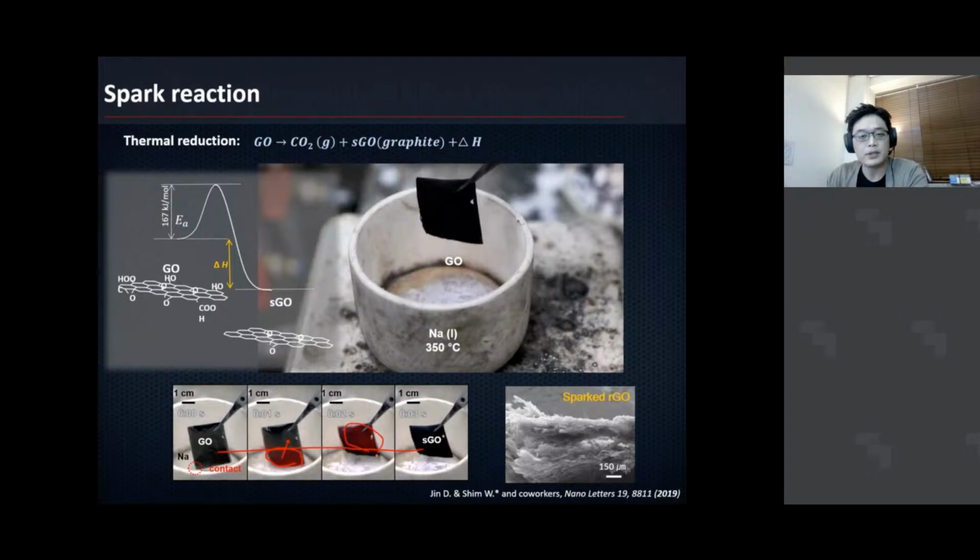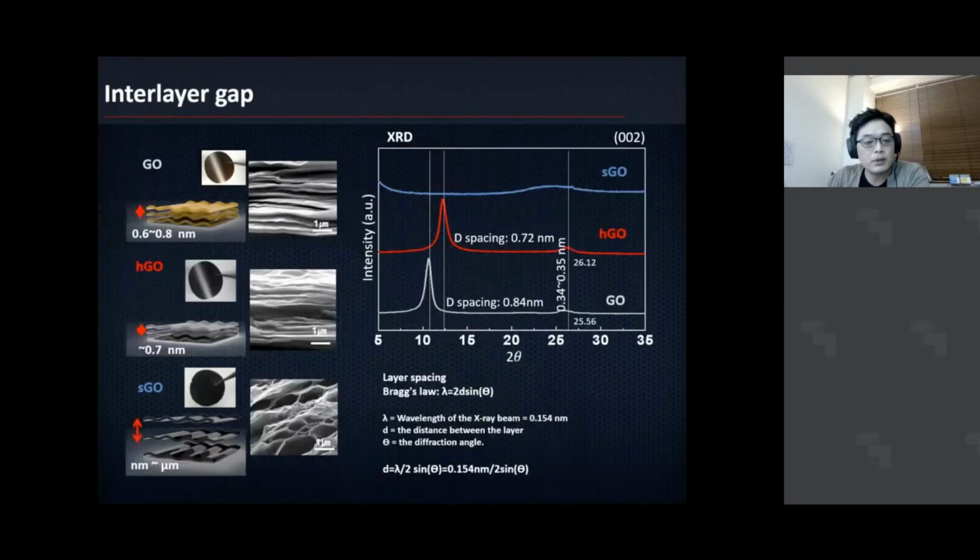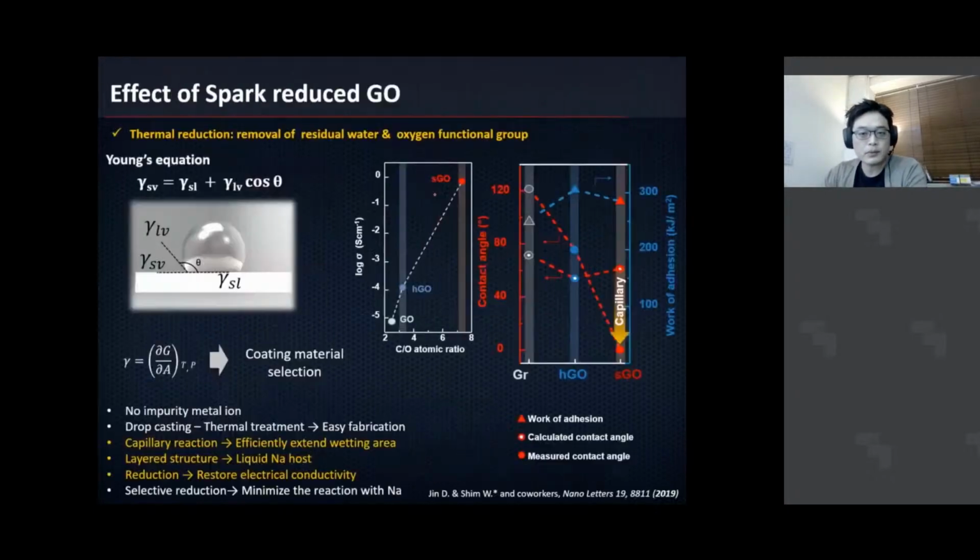That's the fires on it. Okay. So after that, if you look at the microstructure, the morphology of that microstructure, that's the typical graphene oxide. There are many gaps which are larger than 5 angstrom in length scale, and even in XRD, the plane that will index this, the 002 plane, will be gone because it's out of range of the XRD instrumentation.